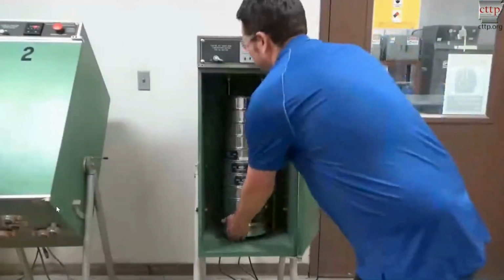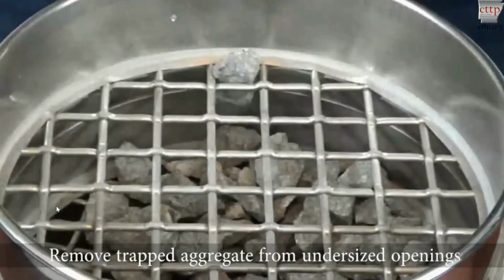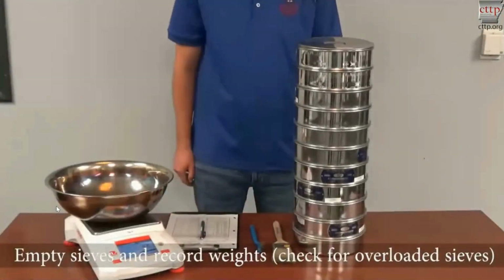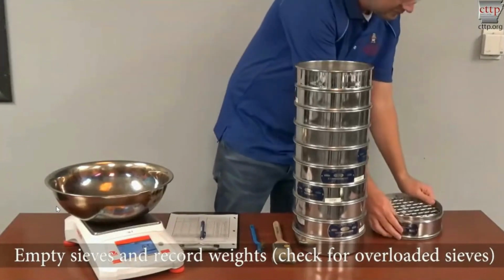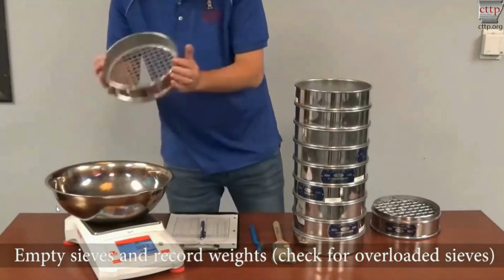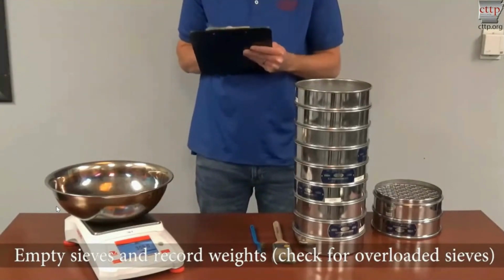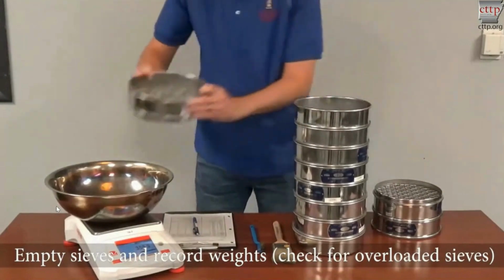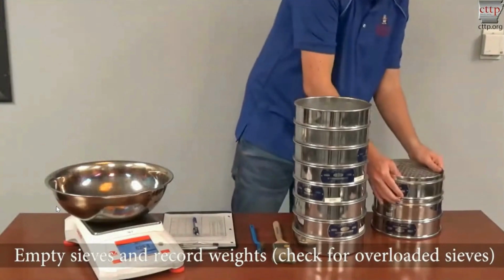After sieving, remove each sieve from the stack. Remove trapped aggregate from undersized openings. Empty each sieve and record the weight of material retained. During this process, check for overloaded sieves. Note that individual or cumulative weights may be recorded, and the method chosen will affect subsequent calculations. We have a standard table, so you need to fill up all the sizes and all the retained weight for each mesh.